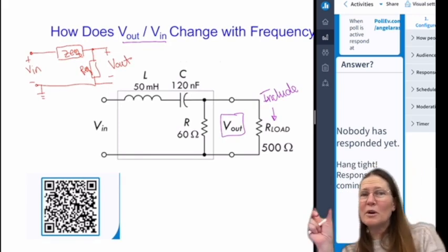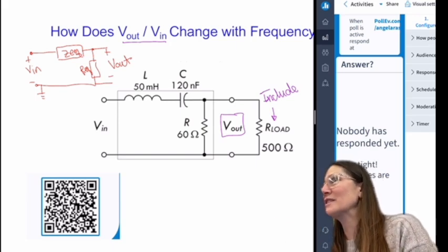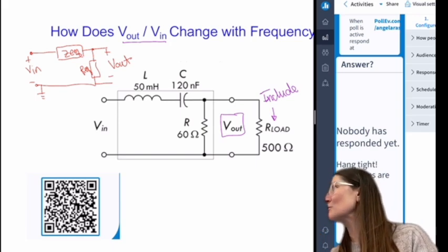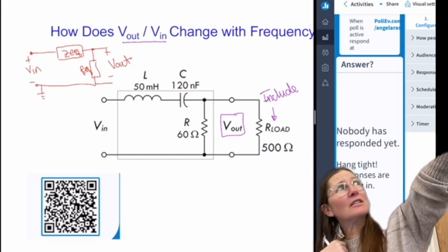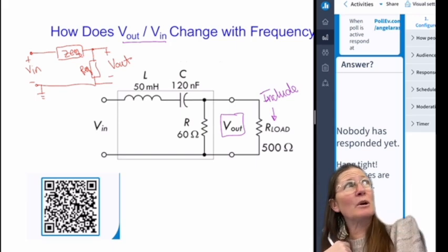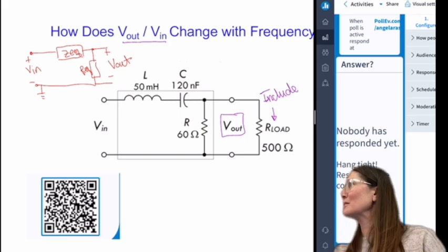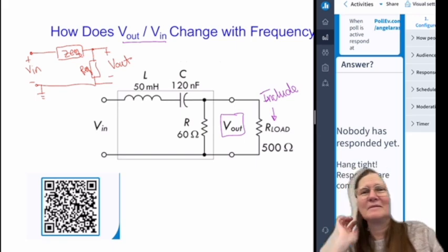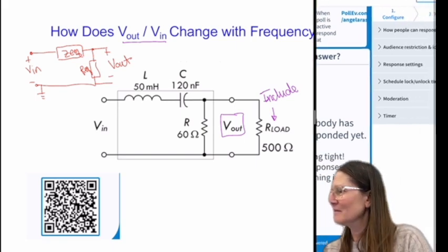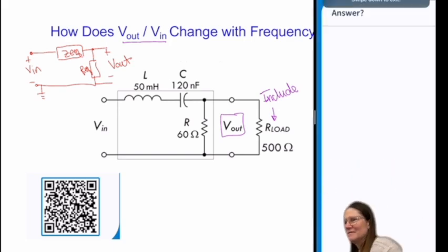So if you put L and C together, you can make a Z equivalent. It's a complex impedance, so it would be treated like a resistance. And then R equivalent can be made, it's the two in parallel. And then hopefully you see it can be a voltage divider. Does that help?